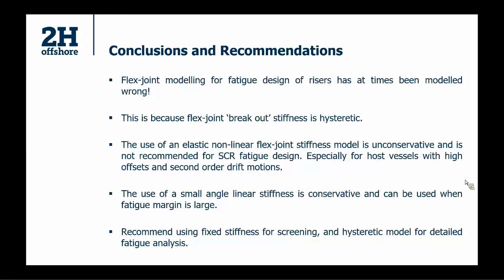Now we can come to the conclusion and the recommendations. The traditional way of flex joint modeling method for fatigue design with catenary riser is incorrect. This is because flex joint breakout stiffness is hysteretic. To use the elastic nonlinear flex joint stiffness model is unconservative and is not recommended for SCR fatigue design, especially for host vessel with high offsets and second-order drift motions.